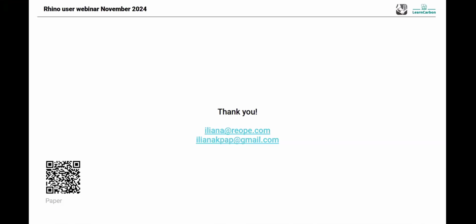If I understand correctly, dependencies get directly installed in Rhino. Normally you have a virtual or conda environment to keep dependencies on a per project basis. Is this also the case here, or does it work differently? No, it works a bit differently. How the Rhino people have set it up, you don't need to create an environment. It has a specified path with the installed libraries. So you just need to install the libraries once through the two ways I mentioned. One is directly, at a high level, from the Rhino interface, which is quite easy.